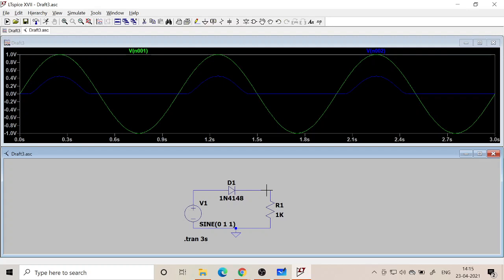That's why I said it's not a good approximation to take the diode to be ideal when the input voltage levels are small. Here you can also measure what the cut-in voltage actually is. The difference between the two peaks is the cut-in voltage. The conduction angle is also much less, right? Just like yesterday we calculated one problem, it came out to be 1/3. So this is similar.